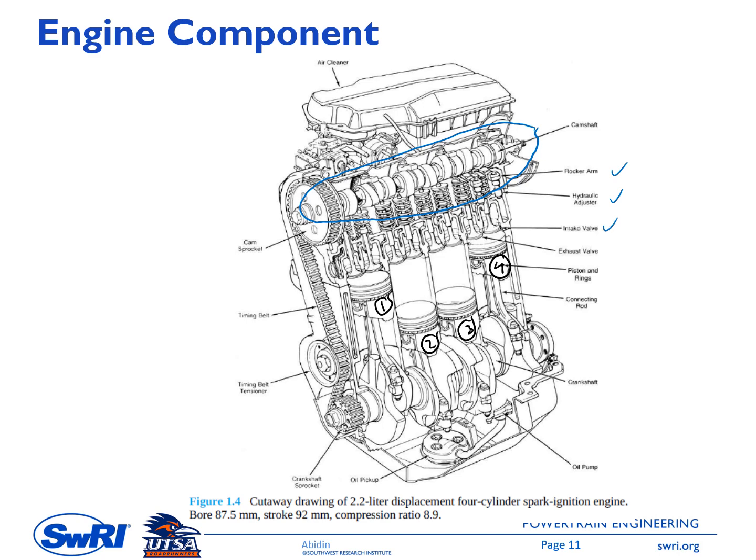This valve train system controls the movement of the intake valve and the exhaust valve as well. Okay, and then another component we have is the timing belt. This connects the crankshaft to the camshaft. So if it is a 4-stroke engine, the cam rotation will be half of the crankshaft rotation.